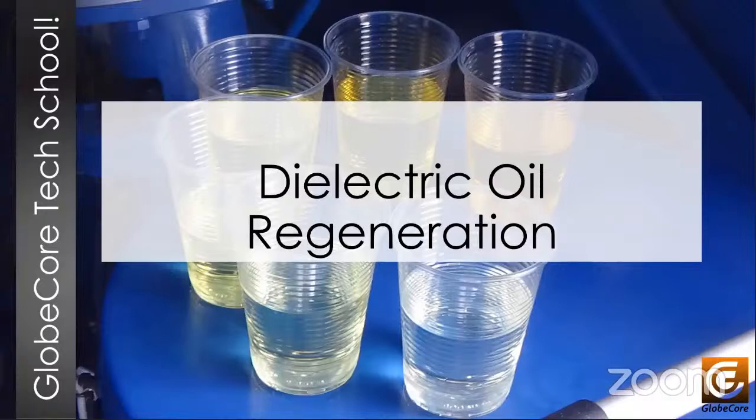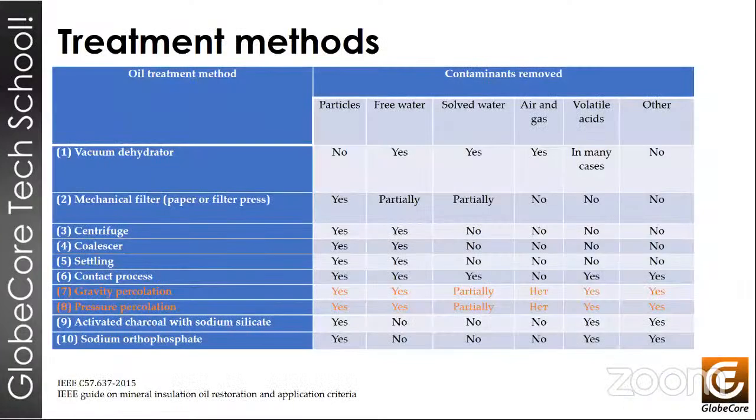In addition, we're going to find out what characteristics of the oil we can improve, because when we talk about regeneration, we'll have to make a clear distinction between regeneration and purification of dielectric oil. So this table here presents the various methods for generating dielectric oil and the capabilities of each process. And this is a very good table because if we do an oil analysis and want to know what process we require to handle the problems with the oil, then we know what to do with any particular type of contaminant. And we can find this information in this table.